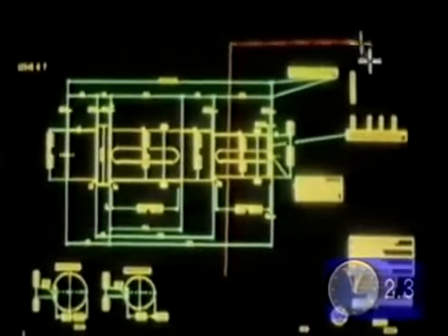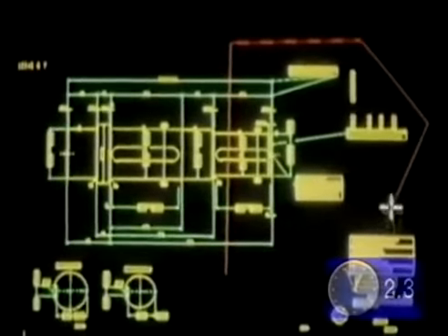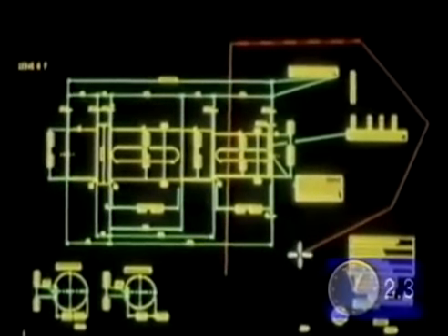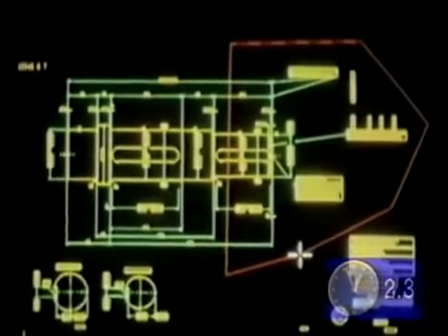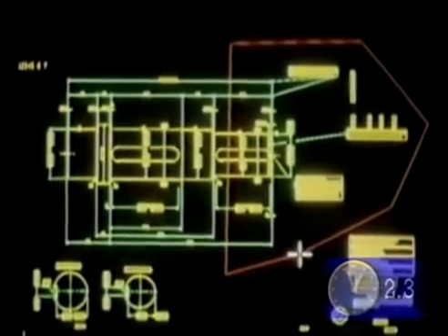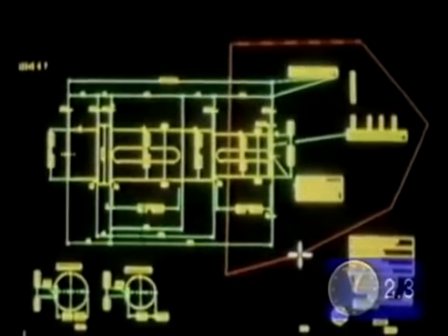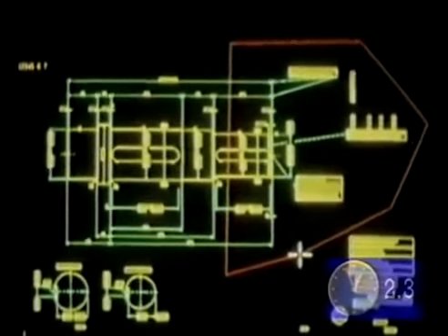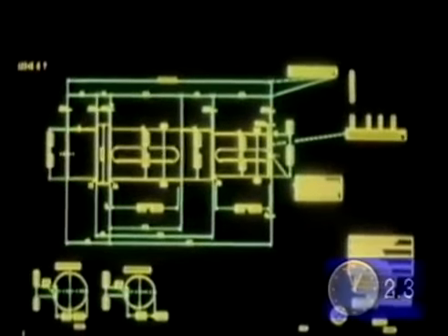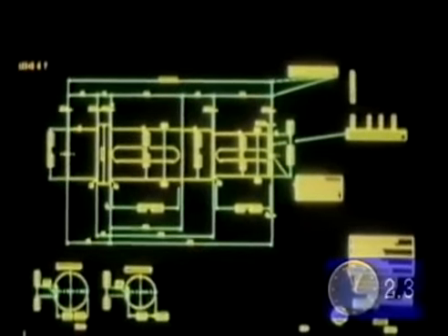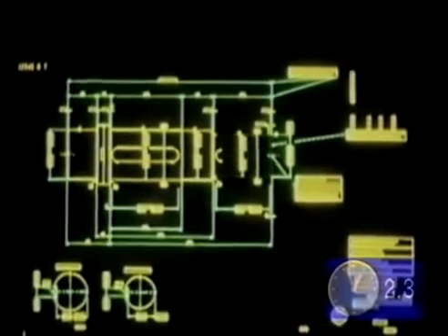We're going to modify this drawing that we've got on the screen now by extending the extension on the right-hand side by 20 millimeters. First of all, I need to tell the system all the geometry that we need to move over. It takes a moment for the system to collect all that data together, and then we can tell it how we want to modify it. In this case, we're going to stretch it, and I can define the axis along which we want to stretch it. In this case, 20 millimeters. The system will then modify all the geometry that's affected and redraw it.